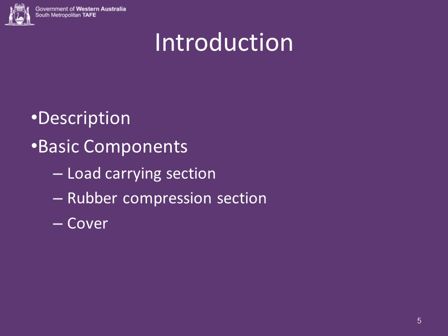The standard V-belt must ride in the sheave properly. If the belt is worn, or the sheave is worn, then you will have slippage of the belt and transfer, and power and speed will change. If a V-belt drive is located near oil, grease or chemicals, the V-belt could lose its capacity through the deterioration of the belt material, quickly resulting in belt breakage or massive slippage.